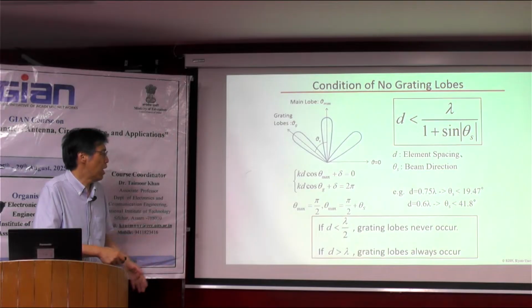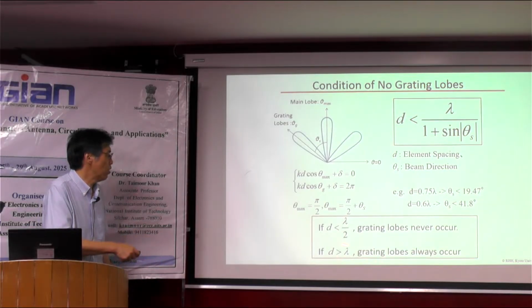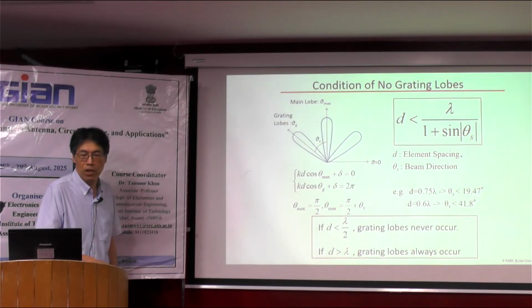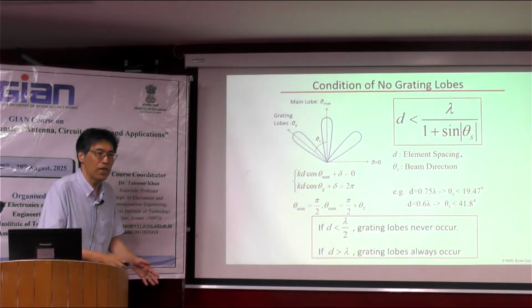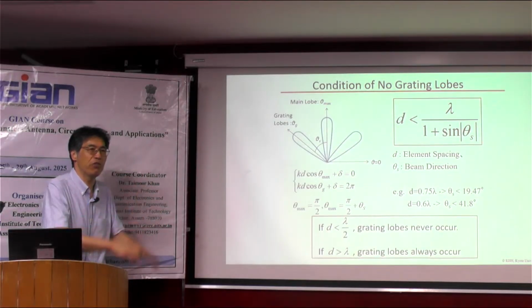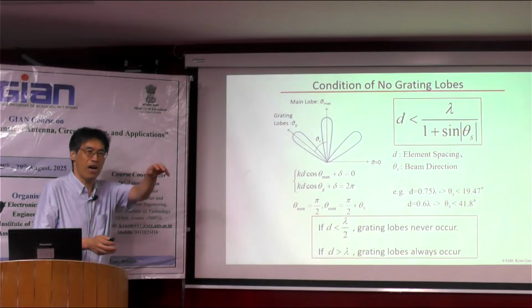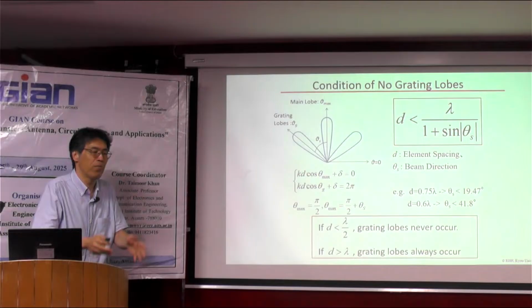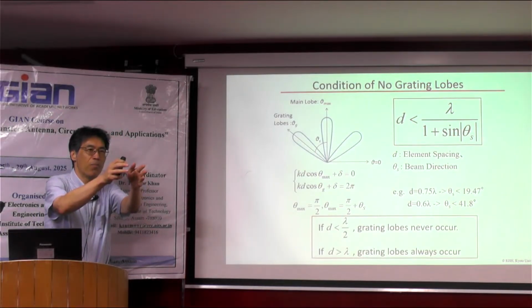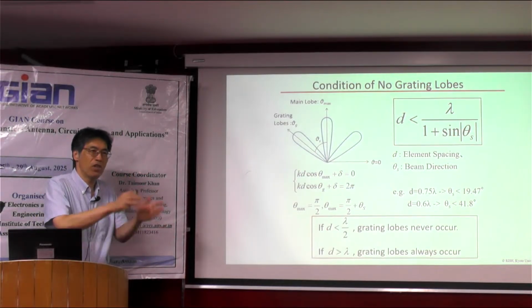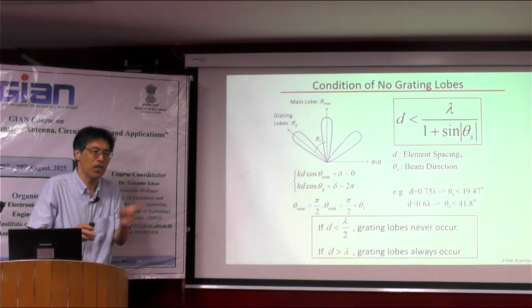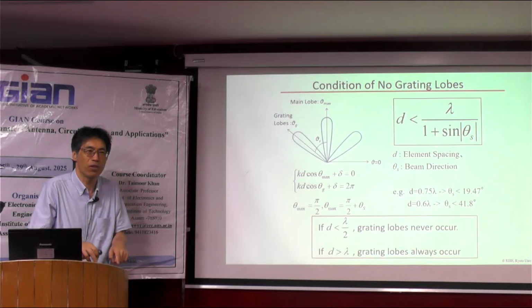And when we put the antennas with a spacing of over one wavelength, grating lobes always occur. So when a grating lobe occurs, beam efficiency suddenly decreases because our target is only one. And if there is no grating lobe, almost all power is transmitted to the one user. But suddenly, a grating lobe with the same power as the main lobe occurs. For example, if one grating lobe occurs, beam efficiency suddenly becomes half.